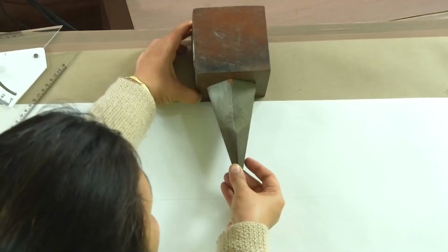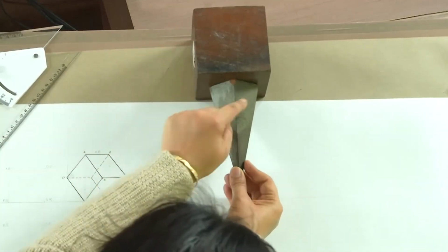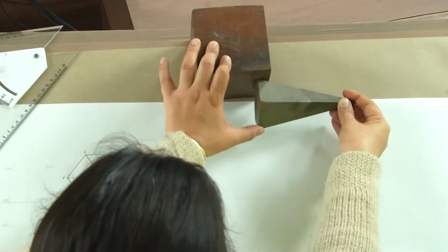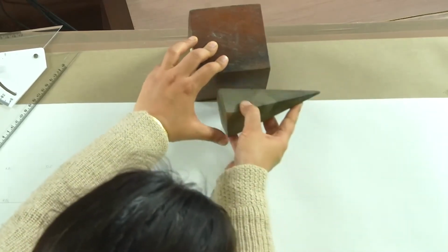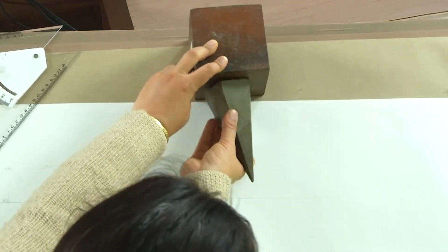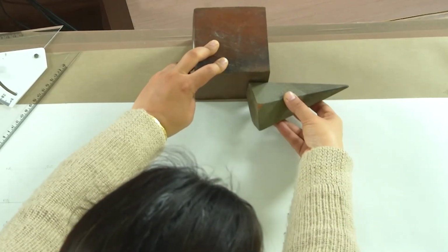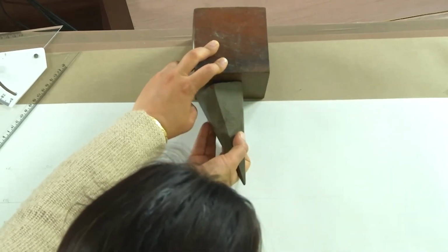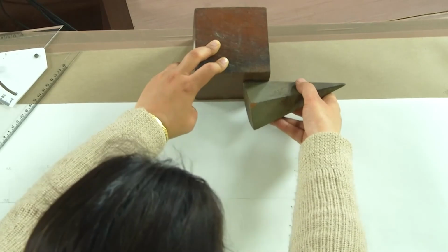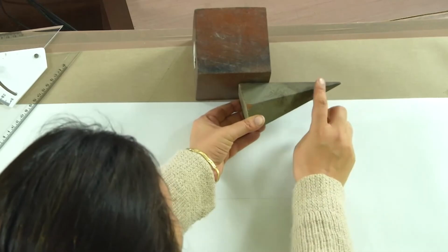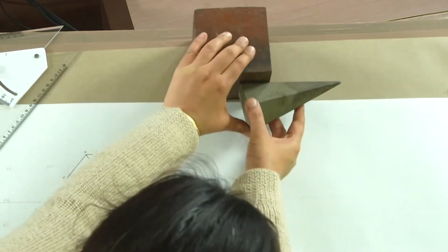We can start with having the pyramid perpendicular to VP, where we will see the true pentagon or the true shape of the base, and then we incline it in such a manner that this face is now in VP. So, we will have to incline it in such a manner that this axis now makes a certain angle with this. If you look at this, this axis is actually making a reverse angle equal to the angle of the cone here. And then we will draw the front view.